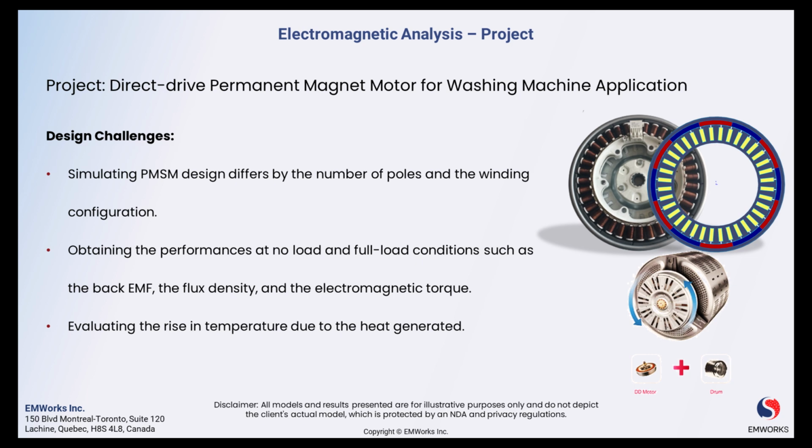So using EMWorks 2D, engineers modeled the motor in CAD with precise geometry. Leveraging coupled magnetic and thermal simulations, they were able to analyze flux linkage, cogging torque, magnetic field strength, back EMF profiles, resistive losses, and temperature rises under operating conditions. This multiphysics simulation provided invaluable insights to optimize motor design for higher efficiency, torque density, and reliability. This project illustrates how EMWorks empowers engineers to develop superior electric motors through comprehensive virtual prototyping.